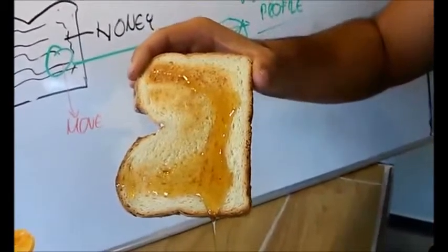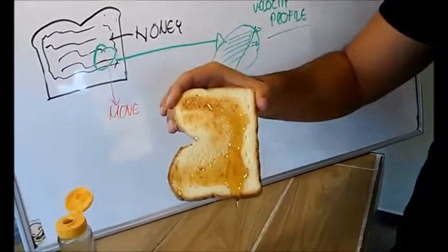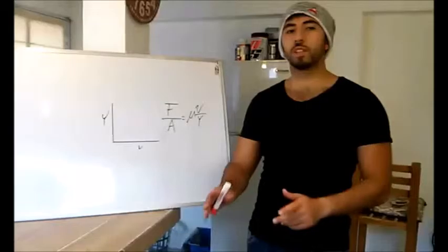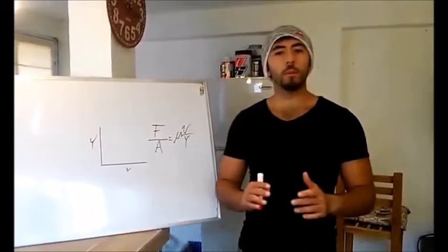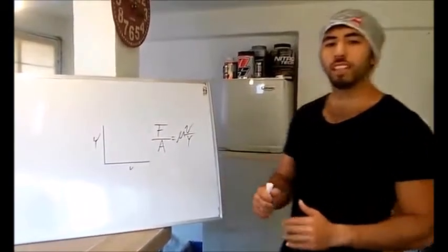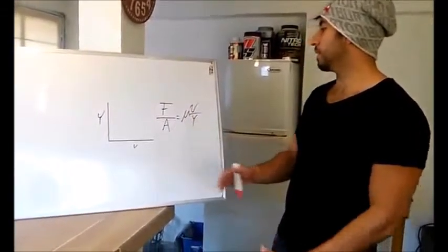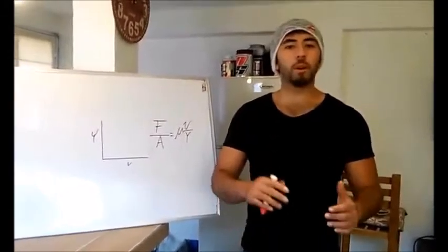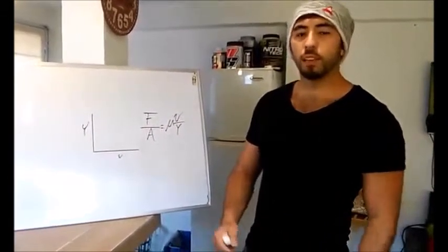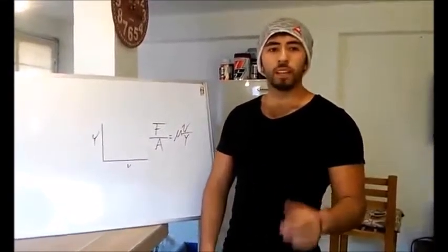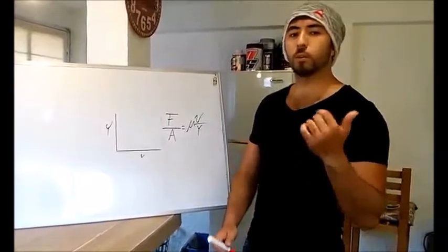We see it moving faster, and the friction coefficient decreases, and therefore the shear stress as well. Once it reaches the steady state, we must apply a shear force F to keep the motion of the upper plate. This force is given by that expression, where the viscosity is expressed with the letter mu. The viscosity is a property of a fluid that opposes the relative motion of adjacent layers in the fluid. Two things about viscosity: the viscosity of gases increases with temperature, and the viscosity of liquids decreases with increasing temperature.